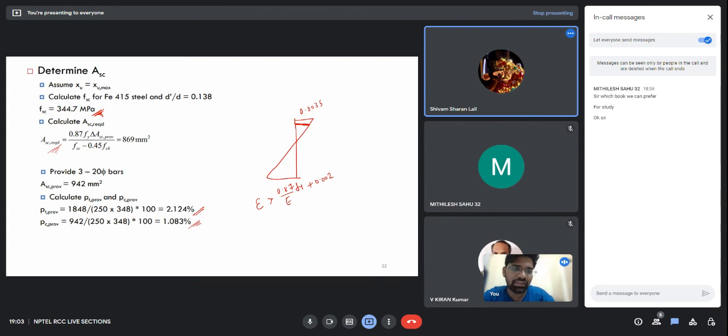No, it is not like that. The strain in the concrete we are always assuming to be 0.0035, and we are assuming that the strain in the steel should be greater than this value. It is not equal. It should be equal or greater than this value. It has not reached this value. It can be said in another way also, no?